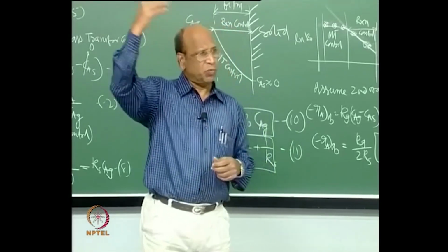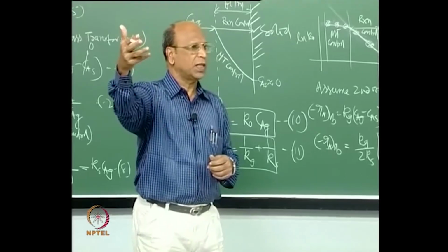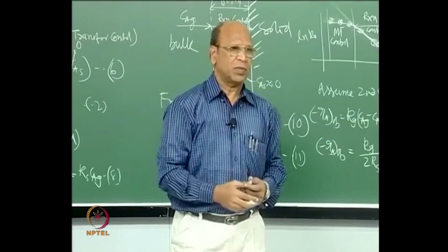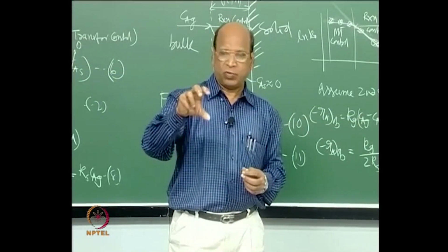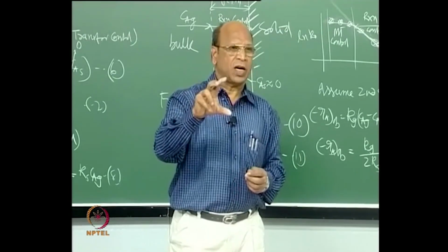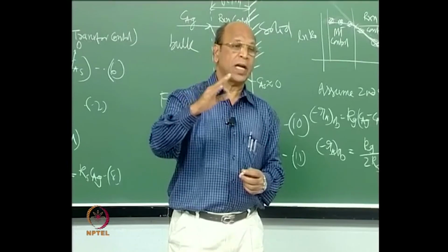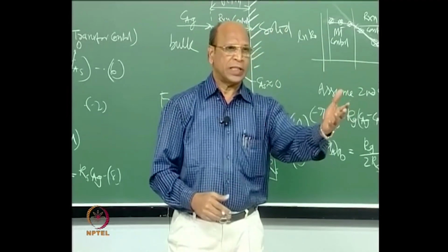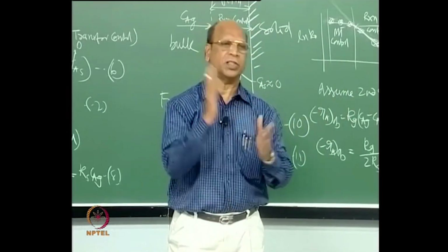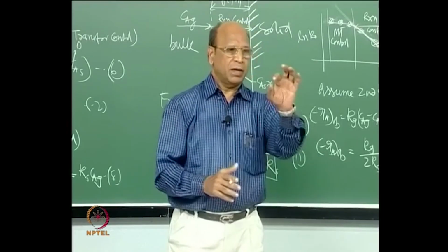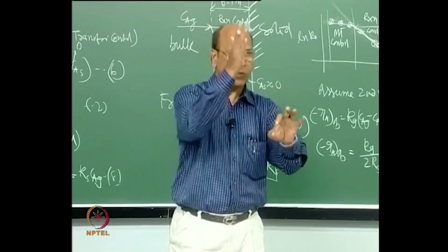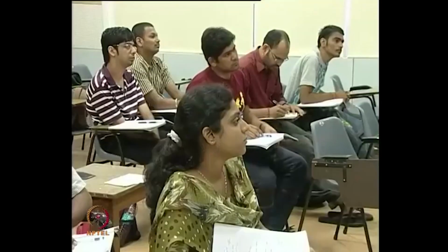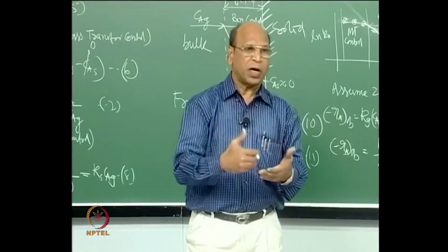So when I use very large velocities, if not infinite velocities, then for providing 8 hours, 10 hours residence time, the length of the reactor should be very large. And for a plug flow reactor, anywhere you go, the diameter will not be more than 8 inches. 8 inches is really the maximum. Generally in industry we go for 4 inches, 5 inches, 6 inches. The reason is that you have to maintain that flat velocity profile so that you are very close to plug flow. This is the reason why the residence times must be smaller for a plug flow reactor.